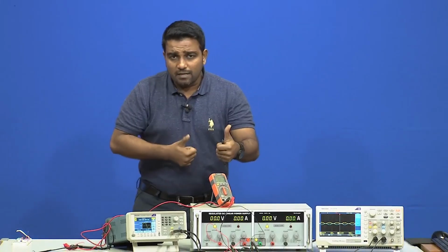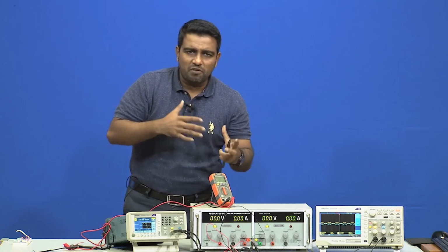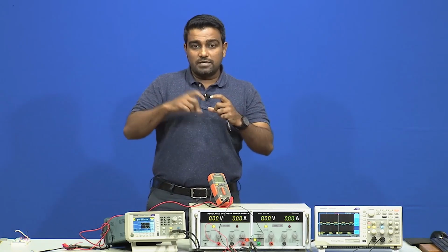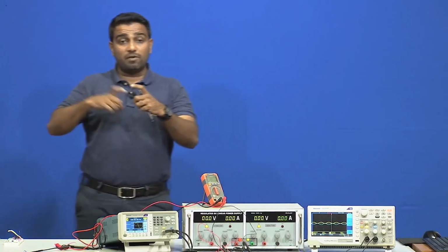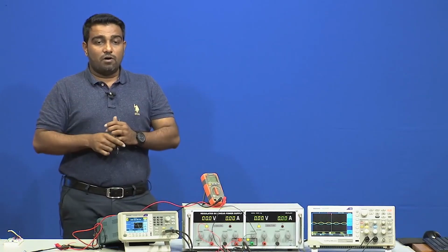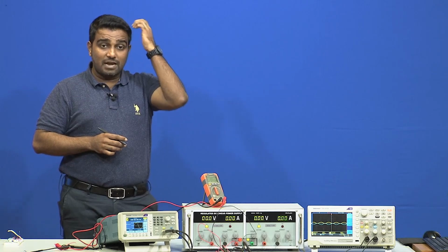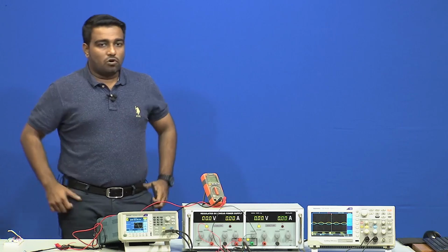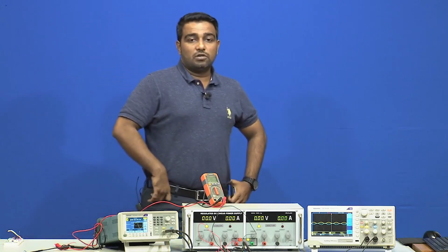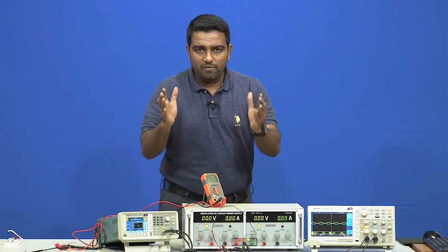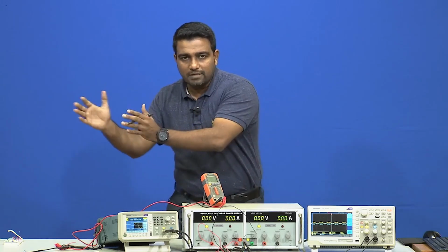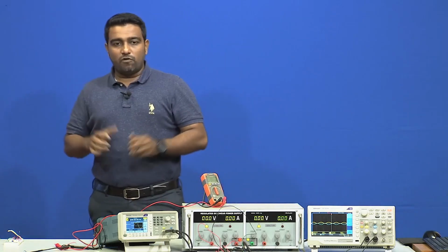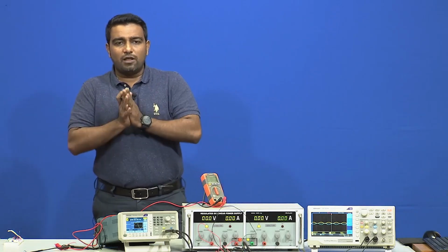That means that here the maximum we can go is about 13.5 or close to 15. We will see that experiment also, what is the range in which the operational amplifier can work. So, that does not mean that when we say infinite gain, we have infinite output voltage, alright. So, this is very easy. Like I said, we will break this experiment into a few parts, so that you can take a break in between after every class. So, for now let us quickly recall what we have seen.